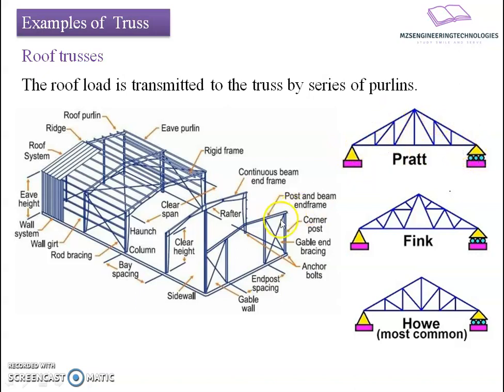These trusses are connected to each other, covering the entire geometry which has to be provided with shelter, and the roof coverings provided over it will generate forces. This force will be the dead load or the wind load coming on it. Sometimes live load will also come due to access if you provide it along the roof.